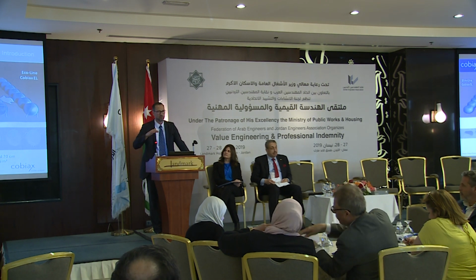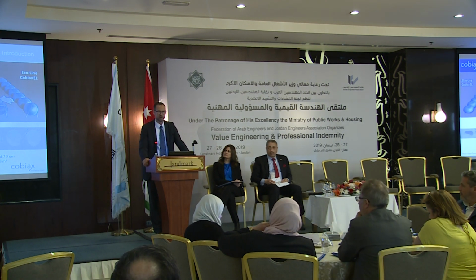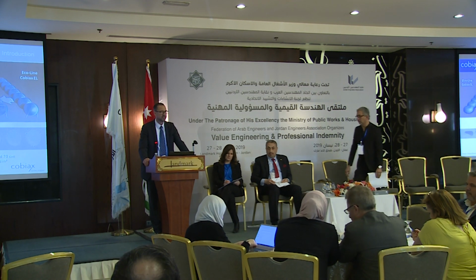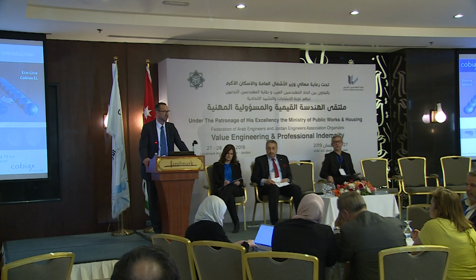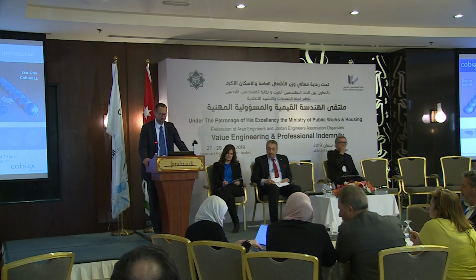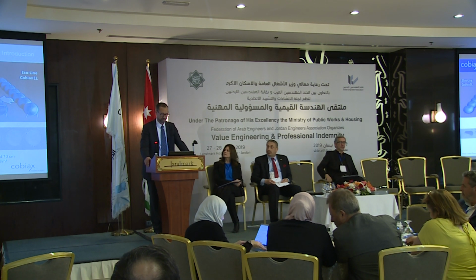First you place a first reinforcement layer, the typical reinforcement of a flat slab. Then you place these void former modules, and then you add the top reinforcement layers on top of them, and then you can start concreting.